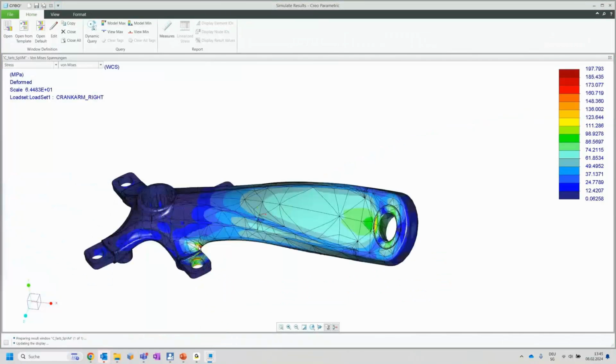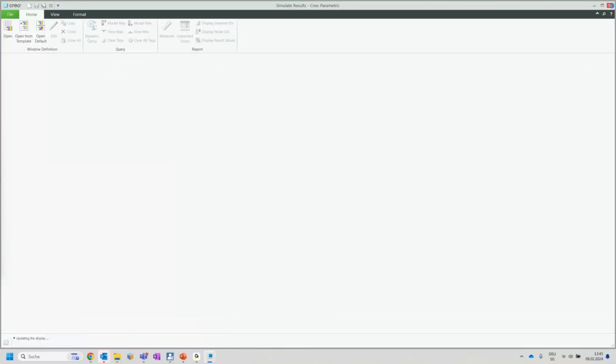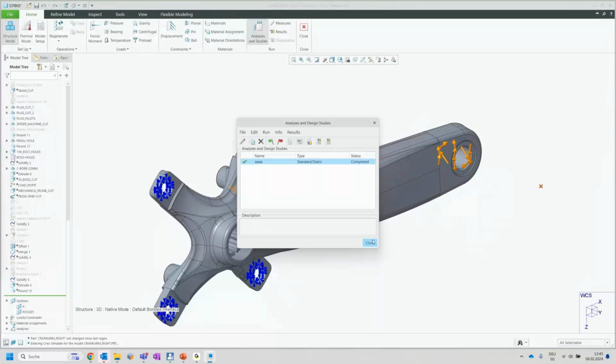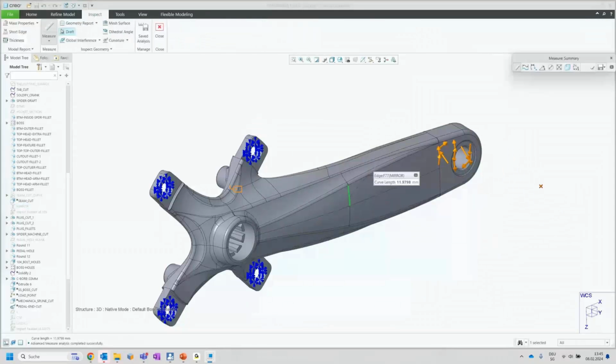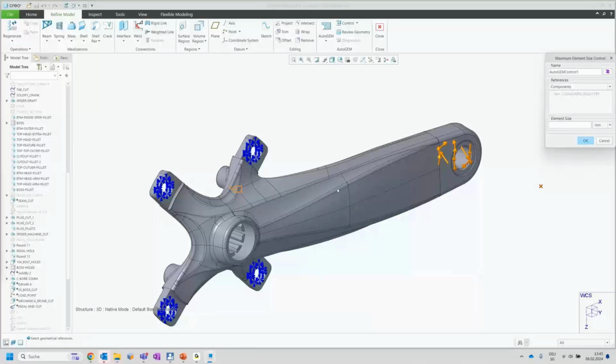Therefore, we are doing the next step, and if we want to see what happens if you're refining our mesh. Of course, we should know how big this component is. Therefore, I'm going for inspect this line here. It's 12 millimeters, and with this information I'm going back for mesh refinement. I say, okay, I want to have a maximum mesh on the whole component of, what is it? Let's do here 9 millimeters.